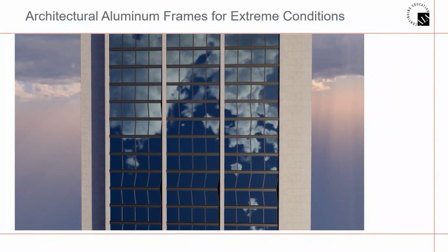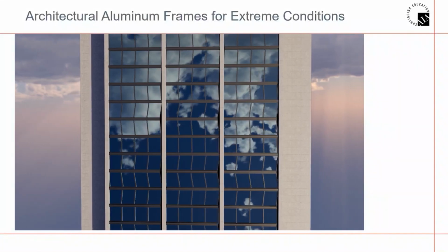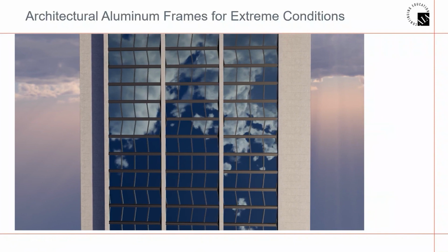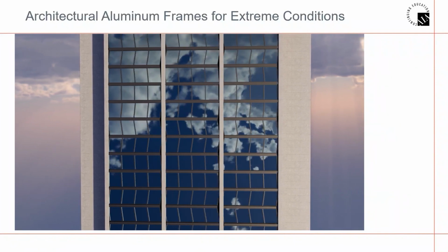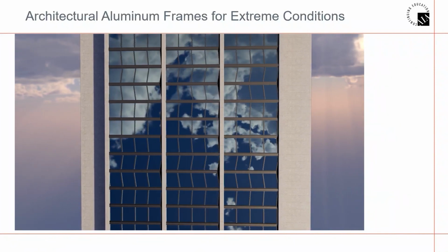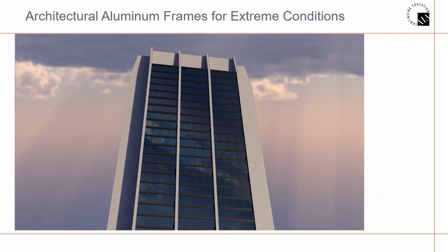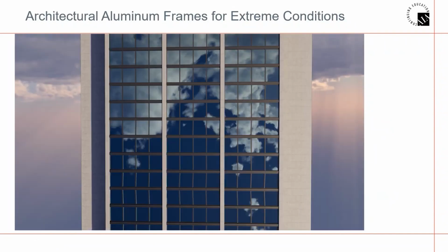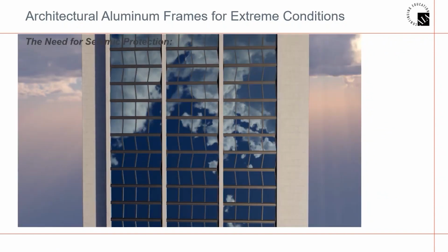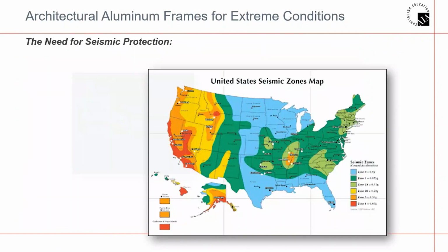So your curtain wall has to be designed with large glass pockets with systems that are designed to slide, the verticals slide past each other, joints, anchors that allow for movement, and large glass pockets around the glass to allow for movement of the frames before they come in contact with the glass units, breaking them.